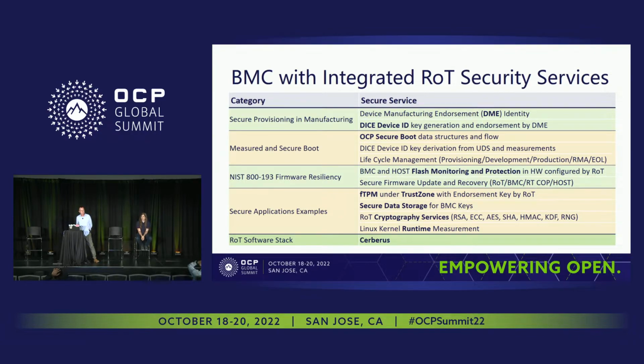That would not be part of the DICE boot, so it would not change with the layer 0 changes if they are required, and that would allow a static, unique identity, which will be the same and will not change through running different firmwares, whether in manufacturing firmware or later on if layer 0 needs to be patched in the field. It will have a separate DICE device ID with the classic and the specifics of the DICE with full-blown.